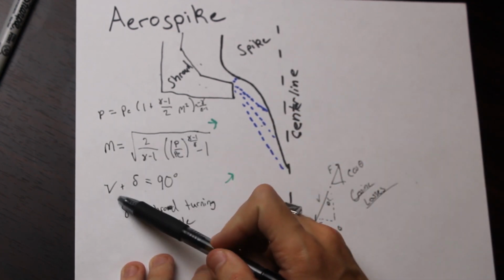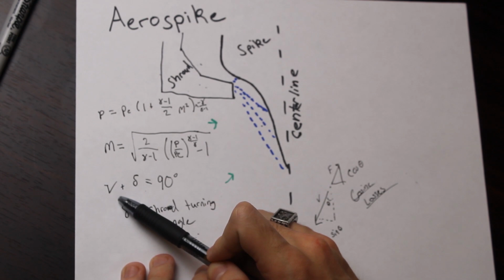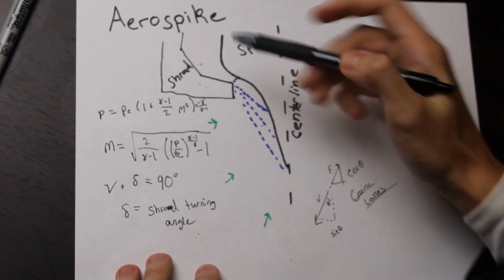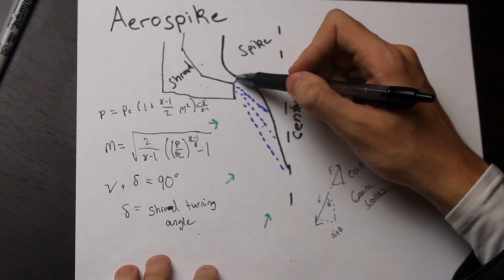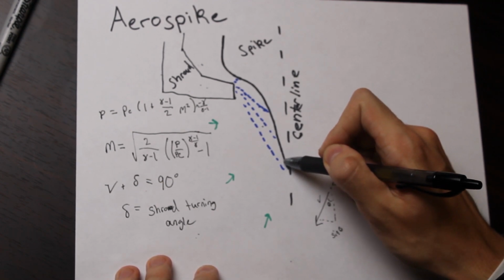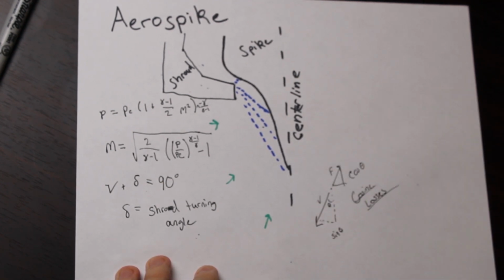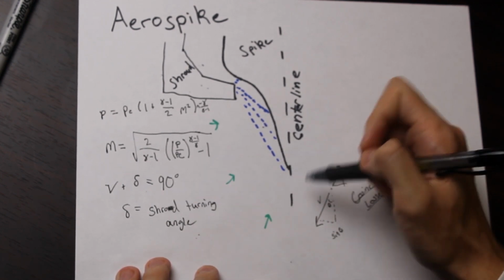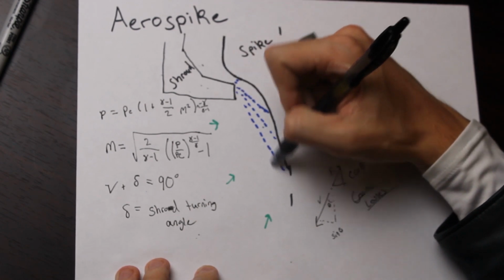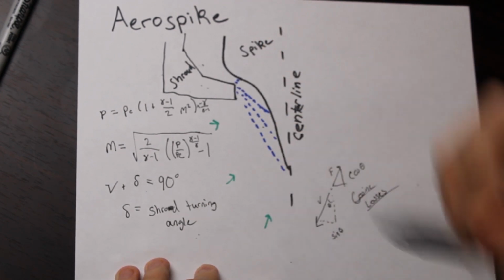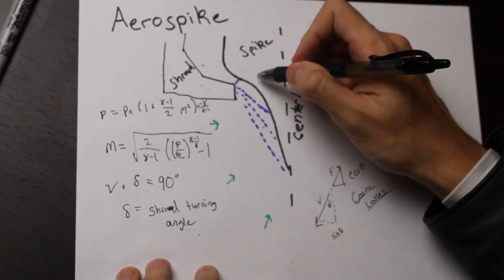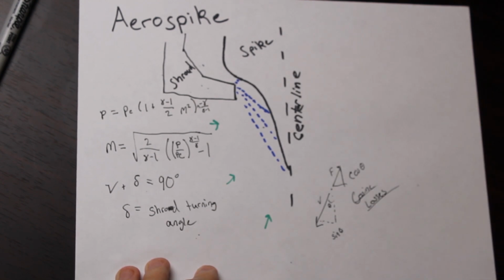So what this really says is that, remember how we were talking about at low Mach numbers, the flow can turn a lot. And at high Mach numbers, the flow can't turn very much. So what that means is that here, where the flow is slow, it can turn and go straight like that. But here, where the Mach number is very high, it can only turn a little bit to depart the shroud at 90 degrees. And 90 degrees we've just defined as straight down. We're saying that the flow essentially has to make a right angle turn from where it leaves here to where we want it to be. So the flow is coming in perpendicular to the direction of travel of the vehicle, and we want the thrust to be 90 degrees offset from that vector.